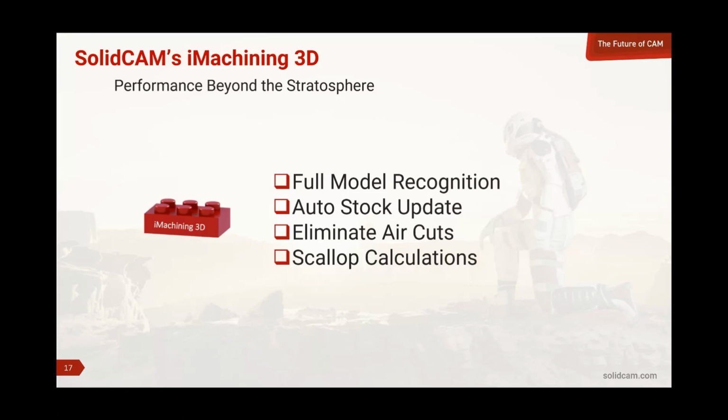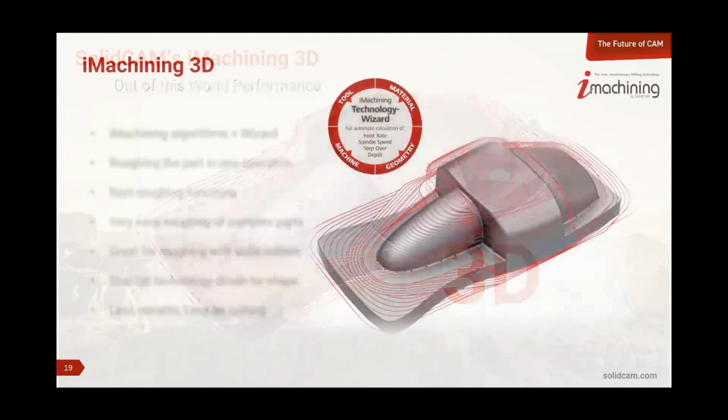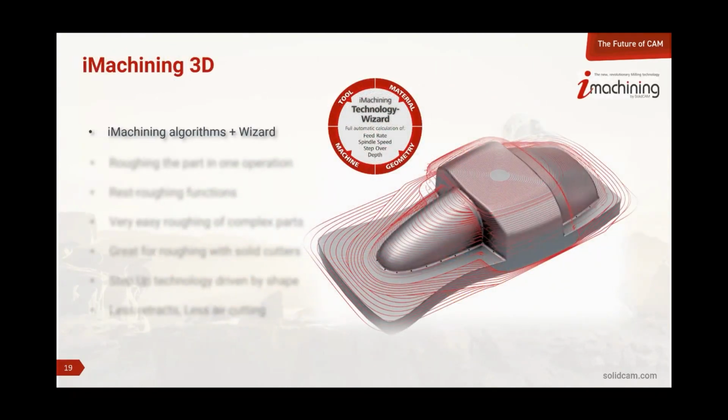Well, with iMachining, the scallop calculations allow us to assign what we want those staircases to be, and you can actually bring the model into a near net finish condition very quickly and very effectively with the roughing operation. And in many cases, eliminating the need for that secondary semi-finishing operation that takes quite a bit of time to do. So let's take a look at how this works.